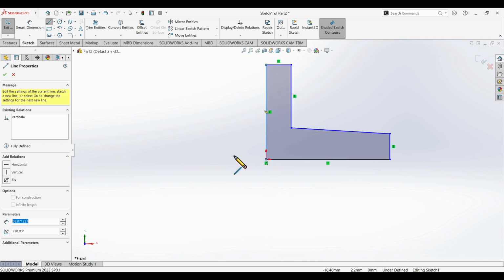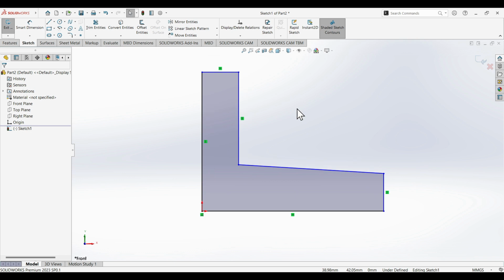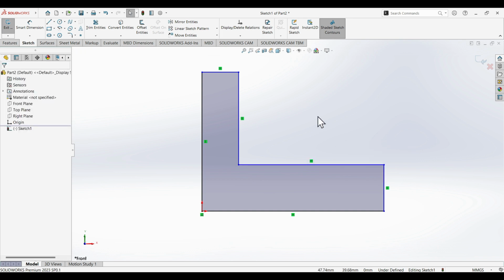While drawing, you should not bother about the geometrical appearance or dimensions of the sketch. You can apply it later as well. We saw that while drawing, this line could not be horizontal. It got some inclination, so no need to worry. I can apply it later as well. Simply click over this line, and I will get those relations in the top dialog box. Here I can choose make horizontal, and it will be horizontal.